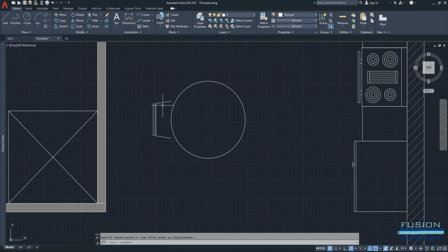If we go back to the drawing, I'm simply going to extend the lines of the chair to meet the edges of the circle. So I'll type in EX for extend, press spacebar or enter, click on that line, escape, and I've got my chair. Now I need 4 of those, so I'll select all of it. I'll make it a group just to make it easier.